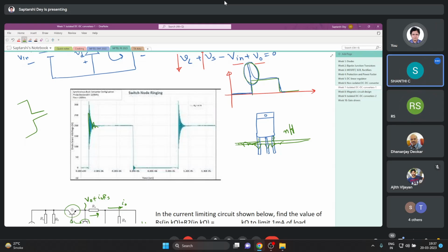That is the thing, you will not get to see the dip in the current. Current cannot change fast in an inductor. The current will look continuous to you. But the di/dt voltage is very large. A small change in a very short time also gives rise to a large voltage.